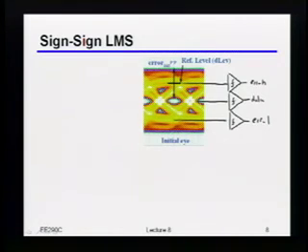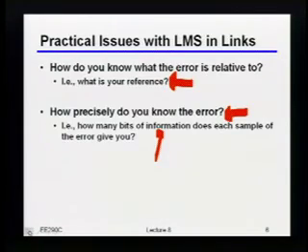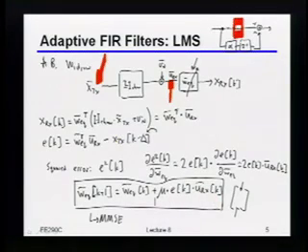Okay? Because as it turns out, and the real details of this are actually hard to prove, because what you're really doing is correlating these things against each other, you can think of it as long as the quantization error you get from doing those sign operations is uncorrelated between the two things, you're still going to get the right answer on average.